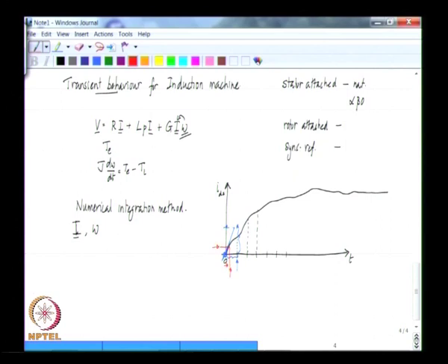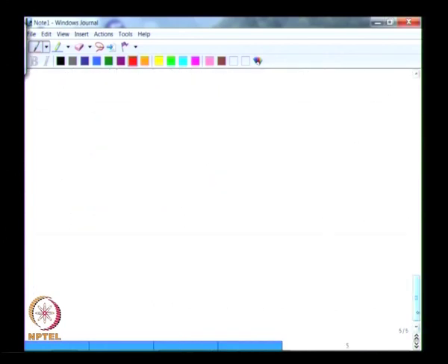What you do now is, you know this value is known. So, now find out what is the slope of IDS at this point, and from the slope of IDS at the next time instant estimate what will be the second value of IDS. Now find the slope again and estimate what will be IDS at the third instant, and so on. Like this one discretizes the x axis and tries to find out the solution step by step. So, how is that done? You basically have to write a code which looks something like this.